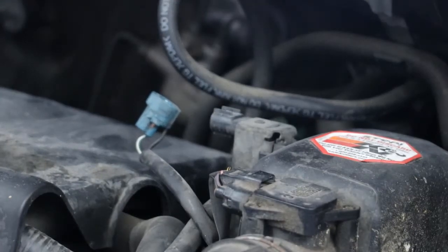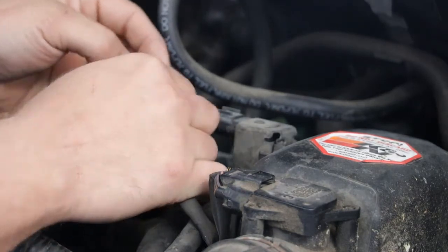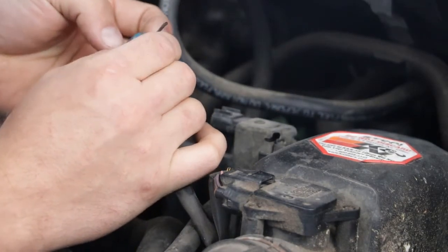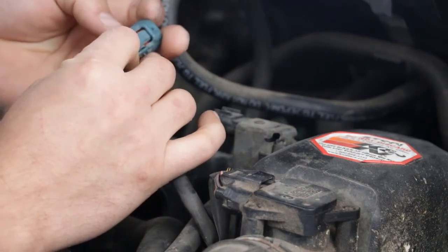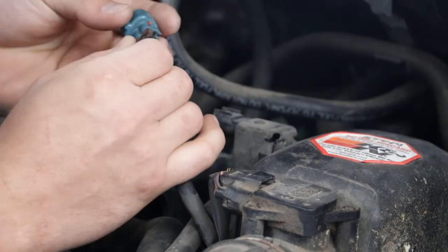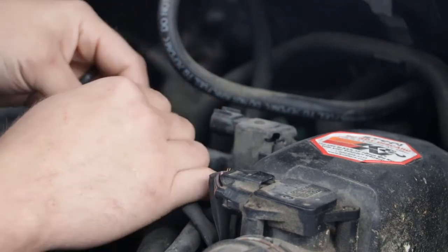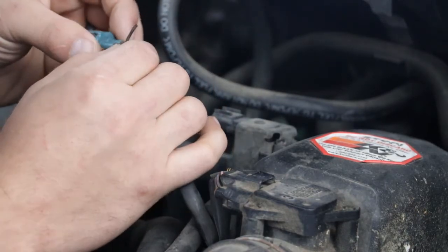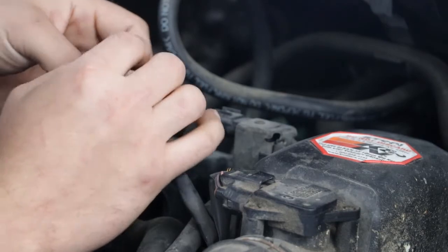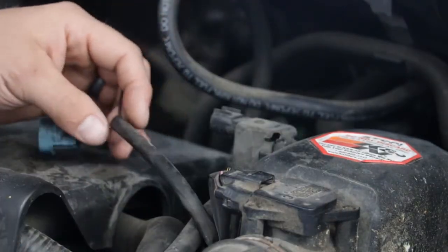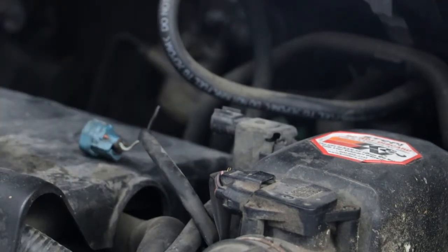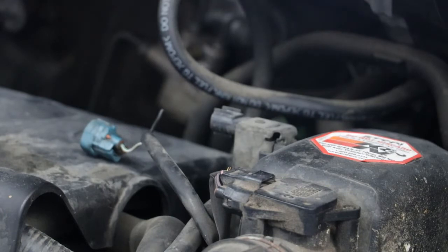Now I know a reason why the purge valve isn't working. As you can see, the cable has broken off, and the purge valve is not even functioning because the connector is broken and ripped off. So I don't know if the last shop did that, or if it's just because it's old or got pulled on. Sometimes people pulling off the air valve pull this off and they rip it off and they don't put it on right, but there's already a big issue. And that's the reason why it won't work. So there's one issue right there.